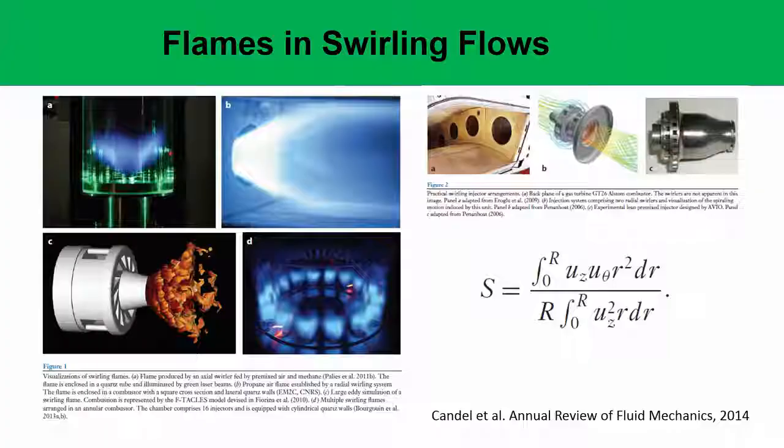So, this is the very important and very basic principle of combustor design, that the residence time of the flow must be greater, okay, than the corresponding chemical time scales, which means that the Damköhler number should be high. So, to make the Damköhler number high, you employ this recirculation. In certain cases you can employ a bluff body also, as you will see later that typically in an afterburner or the augmenter people use bluff bodies, but in the main combustor, which we are discussing right now, you essentially use this kind of swirling flows.